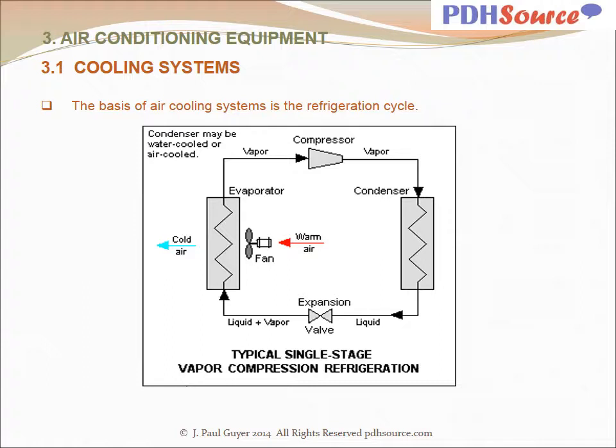to rotate like that, from refrigerant vapor, cooler refrigerant vapor, compressed in the compressor, gets hot, is pushed into the condenser, is cooled by outside air, and condenses into liquid refrigerant, which is pushed through the expansion valve, which causes it to come out of the expansion valve in a combined liquid and vapor state that is cold, and that is pushed into the evaporator coil.